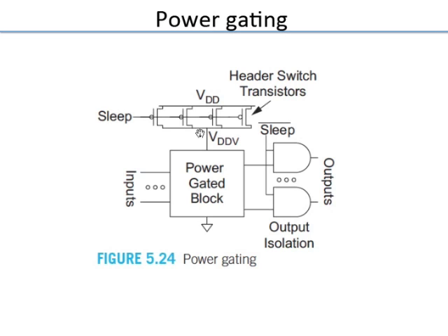That is another thing to be considered. Also, when you turn it on, say this voltage is close to ground, you are essentially turning it on, and you'll have a lot of current initially going into this node to charge up, right? It's like you have one capacitor shorted to ground, you turn on this power gate switch and there's a lot of current which will just rush in at that particular instant. When the current starts rushing in, you will have a voltage drop in this VDD outside on these wires, which can affect performance of some other logic blocks. You turn this on, it creates noise somewhere else.